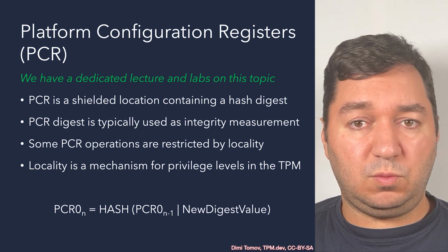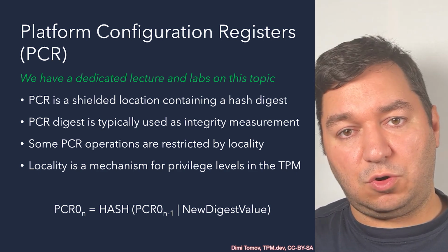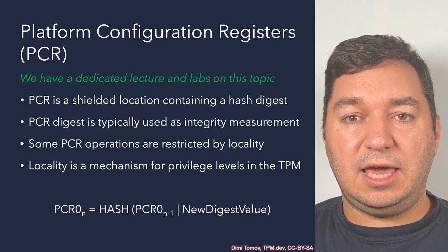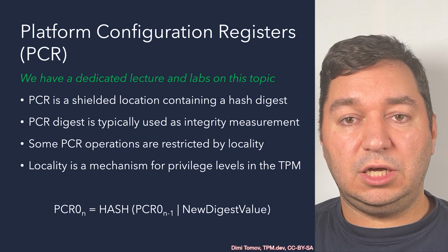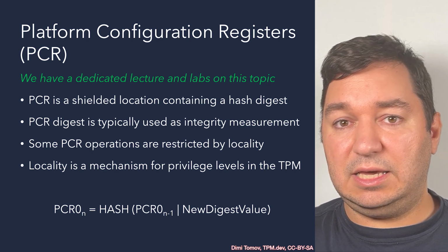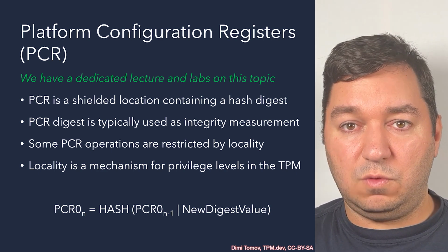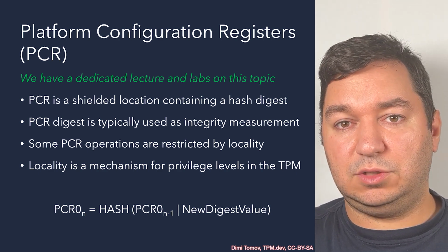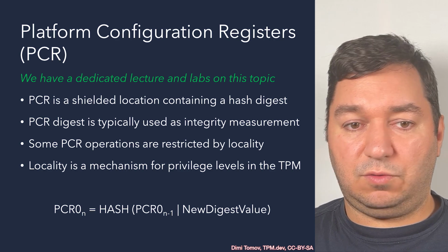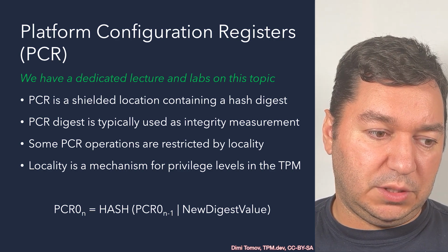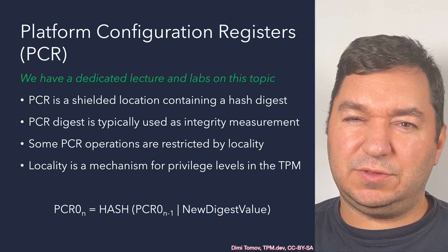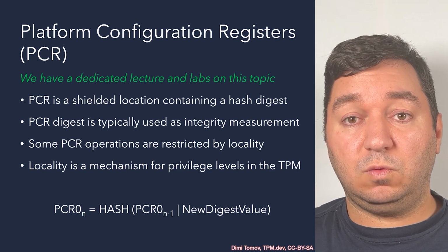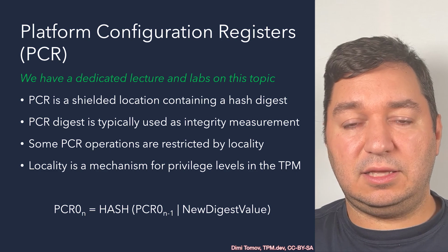This is especially useful when we do measured boot and we measure all the stages of the operating system or the firmware that we're loading, and we inherit the information from before. So as long as we follow the same steps and it is the same system, we'll get the same result, the same digest at the end. And this cannot be reset until the system is powered on and off. So that's great. And of course, this security mechanism about when you can reset it is tied to another property of the TPM called locality, and we'll talk more about that in the dedicated lecture.